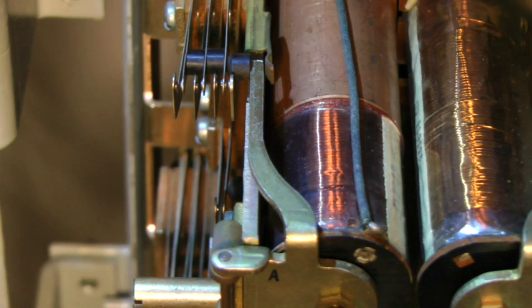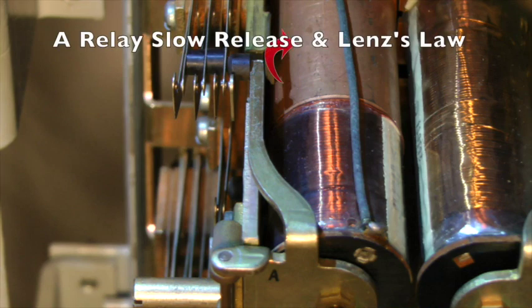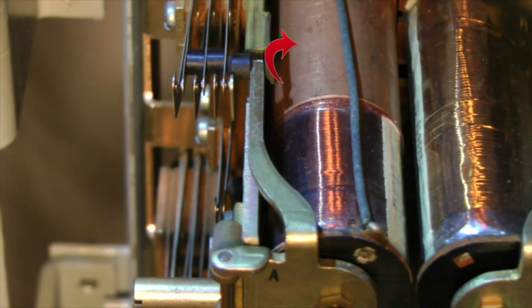The A relay is slow to release to ensure that this holding ground is maintained long enough for the replacement ground path from the first selector to be applied. The slow release feature is accomplished through the use of this large copper slug mounted at the heel end of the relay spool. This enables the application of Lenz's law.